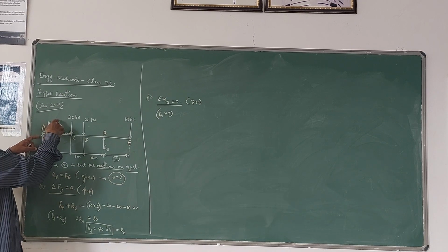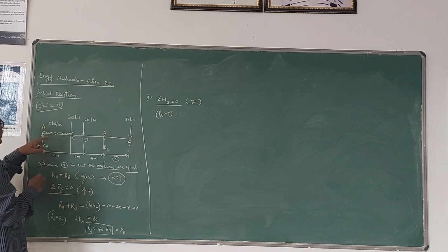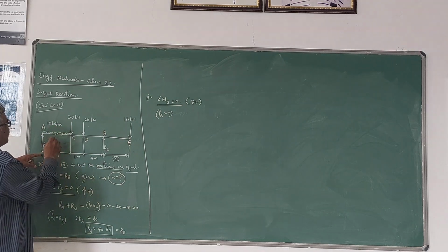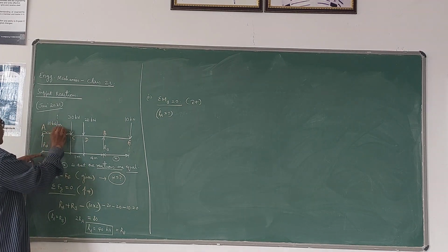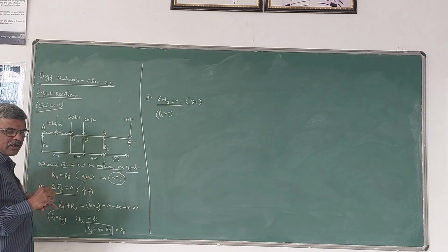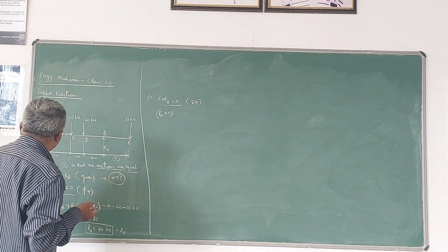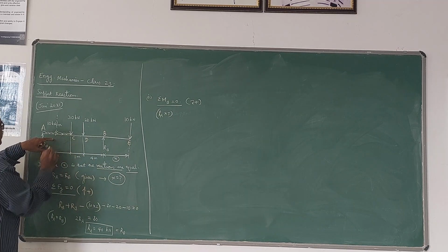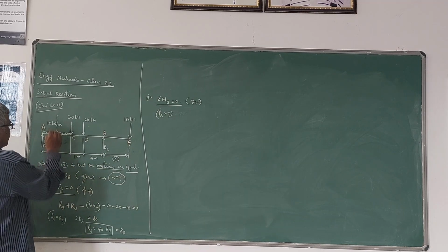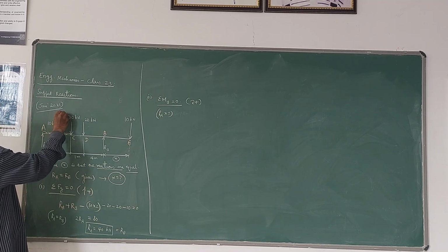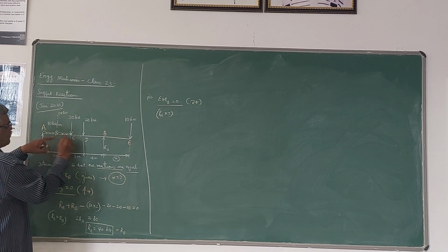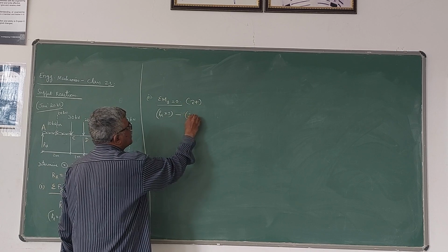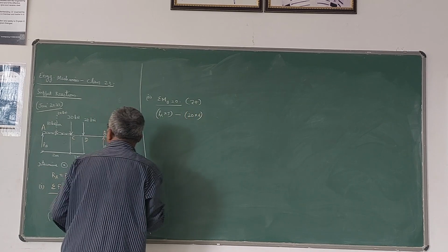Then this 10 kN per meter UDL will be acting at the midpoint. So it is 10 into 2, 20 kN will be acting at the midpoint. That is how we have to take the equivalent concentrated load. It is acting at midpoint. The distance from B will be 4 plus 1 plus 1, so it will be 6. So 20 kN will be acting at a distance of 6 meters from B, and the moment due to that is anticlockwise, minus 20 into 6.